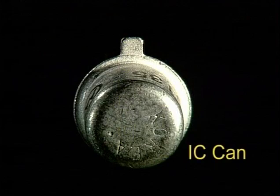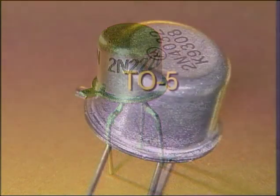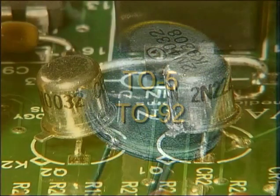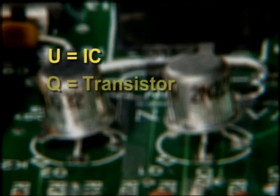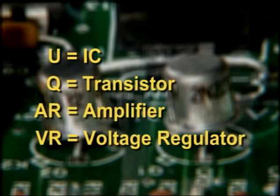IC cans are often transistors or voltage regulators. These cans have a number of long radial leads. TO5 and TO92 are among the most common sizes of IC cans. The reference designator will depend on the function of the IC can. Typical reference designators may include a U for a general IC, Q for a transistor, AR for an amplifier, or VR for a voltage regulator.